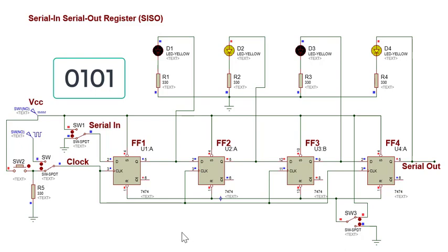If we continue to apply clock signals with SW1 in the down position, there will come a time where all output levels of 4 flip-flops become 0. By permanently positioning the switch SW1 to up position and continuously triggering the clock inputs, you will notice that after 4 clock transitions from 0 to 1, all 4 flip-flops will have high logic levels.